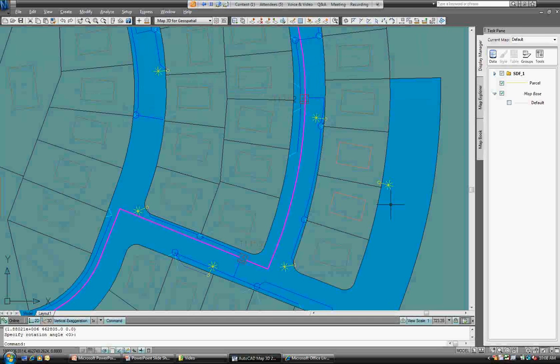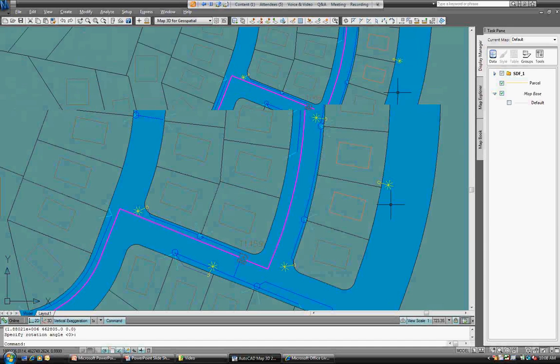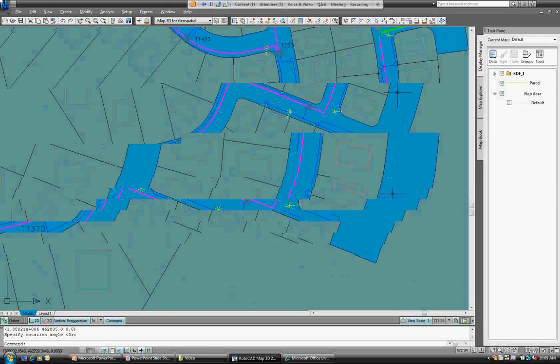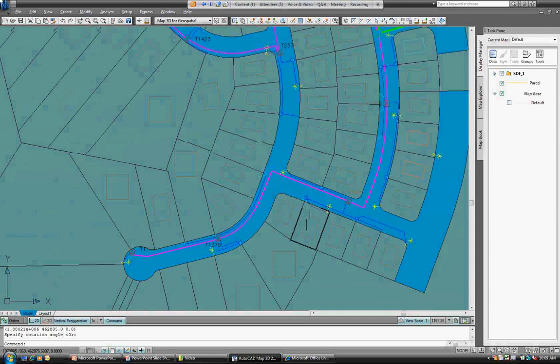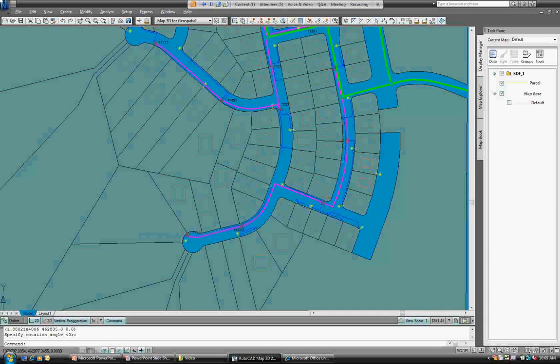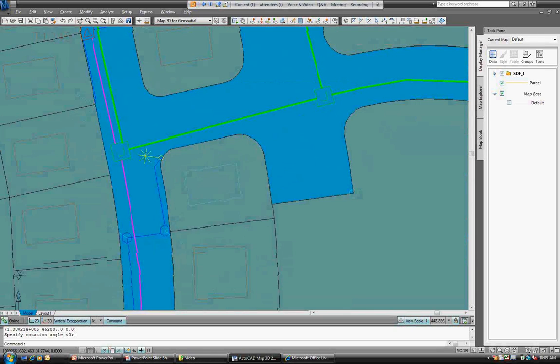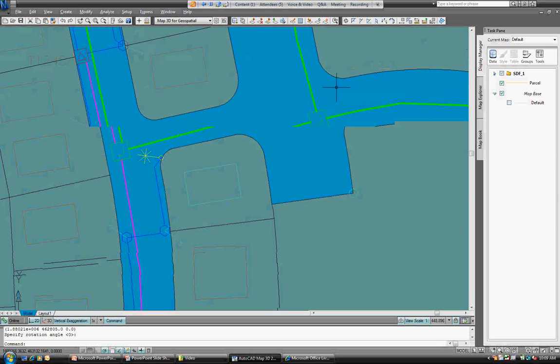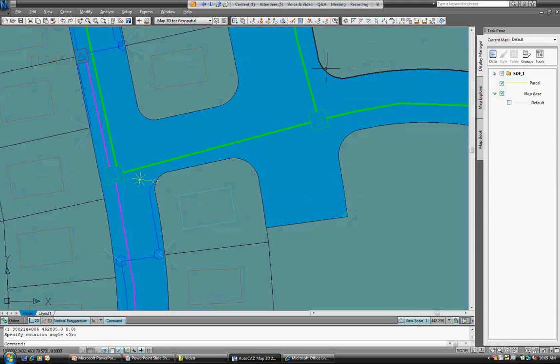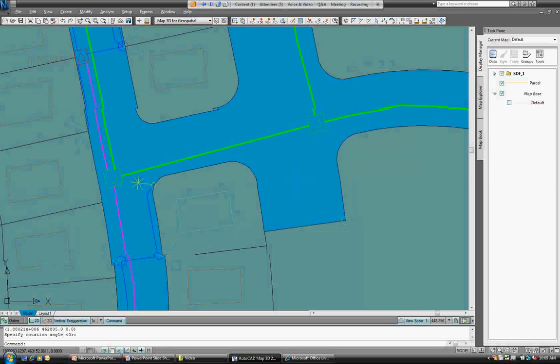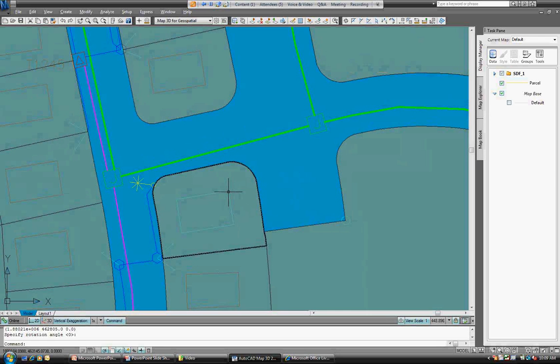How about the bearing command? So let me find my other location here. There we go. Had it marked. So again, we want to locate a street light on this corner, but what we have is the bearing of two lines, one from the corner of the house and one from the corner of this intersection, and the location where those bearings cross is where we want to locate a street light.